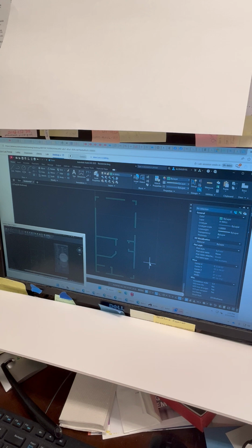So watch this. And remember, with no selection, all it's saying is that these are some general properties about your current drawing and the current state of the view you're in. So here it says the UCS icon is on. If I come over here and I turn it back off, now look what it says. UCS icon on: no, not on.